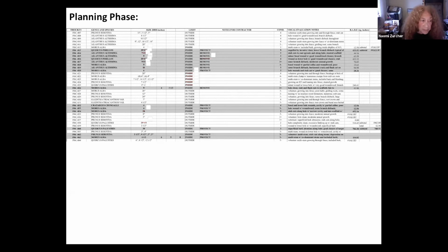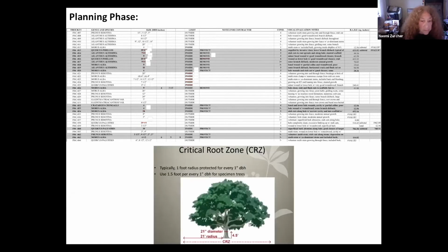The planning phase. Although planning is part of construction's design phase, for our purposes, I have separated them as what we do in planning lays the groundwork for what will happen throughout the design phase. A complete ground-based inventory to be conducted by an urban forester or an arborist of all trees within the project footprint, as well as those trees within close enough proximity as to have their critical structural roots within the project area.